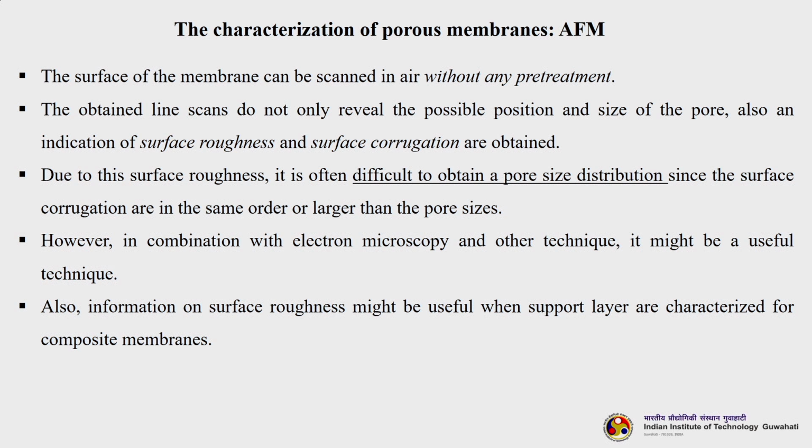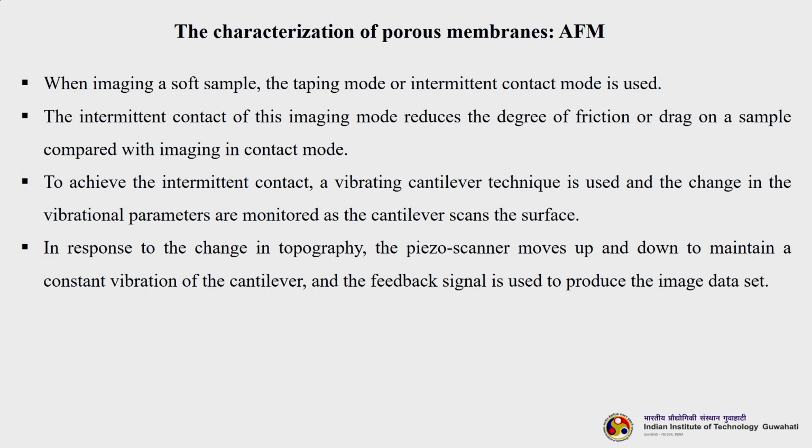Information on surface roughness might also be useful when support layers are characterized for composite membranes. When imaging a soft sample, the tapping mode, or intermittent contact mode, is used. The intermittent contact of this imaging mode reduces the degree of friction or drag. To achieve the intermittent contact, a vibrating cantilever is used.